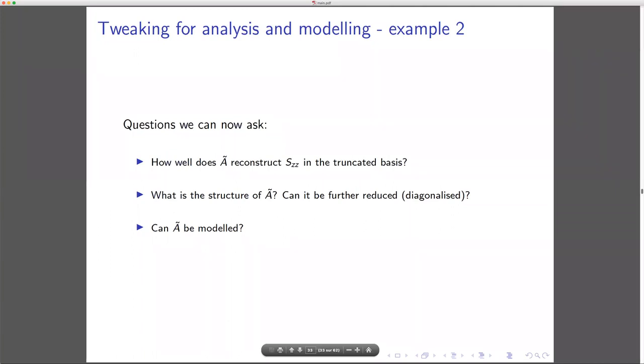How about a simple laminar flow? Let's say I apply LES with Kolmogorov length scale, a very fine mesh, in a simple laminar flow. Yeah, in a simple laminar flow, there's no problem. And in fact, even in low Reynolds number turbulent flows, there's no problem either. There's a paper recently by Petronio Nogueira and Andre Cavalieri in the KTH group, where they're looking at the nonlinear term from a low Reynolds number channel flow. In that case, they're able to compute this without any issue, and they don't have all of these problems. The difficulty is in high Reynolds number turbulent flows. Thank you very much.